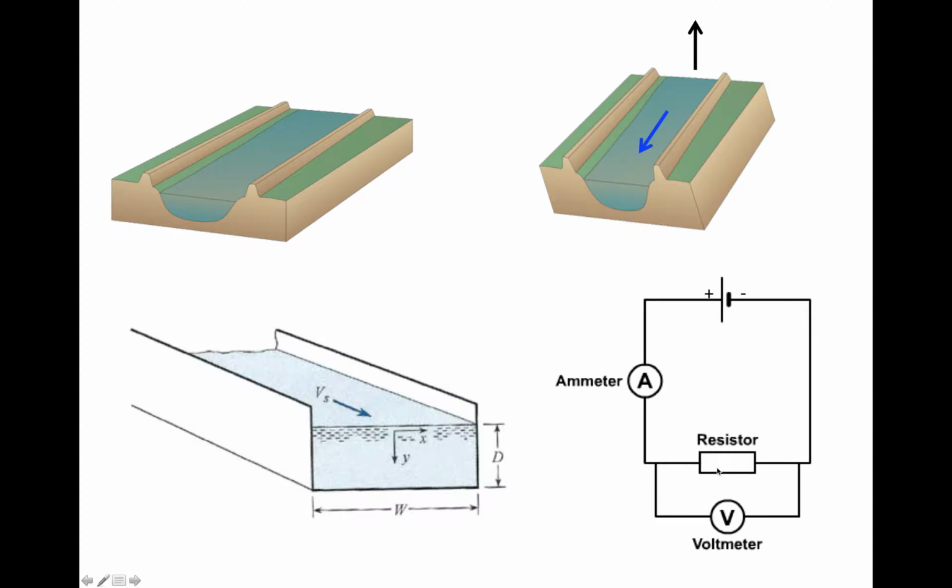And this voltage change across an electric component can be measured using a voltmeter. Sometimes the ammeter and voltmeter are combined into the same instrument, with a dial that allows you to choose if you want to use it as an ammeter or as a voltmeter. But if you are using it as a voltmeter, you have to connect it in parallel with the electric component you are trying to measure. It has to be connected in parallel.